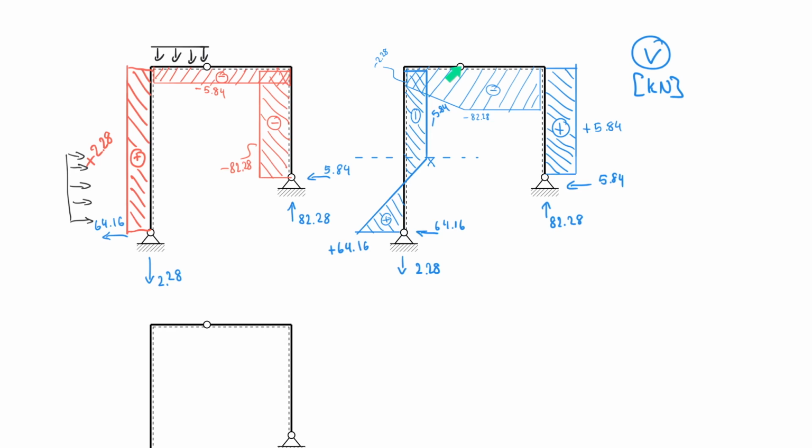So I want to emphasize, yes, here there's a hinge, and often, as I said before, when we talked about hinge beams, students want to think of the hinge as being 0, but that's only true for the moment, and we'll come to that when we talk about this diagram down here. But for now, there's a value here. In fact, it's the value 82.24, and then it starts sloping up.